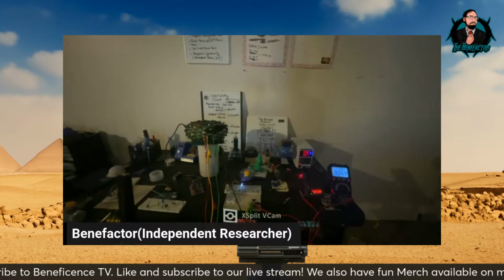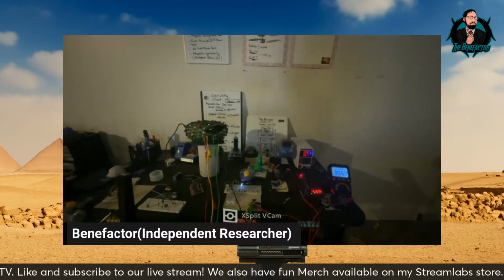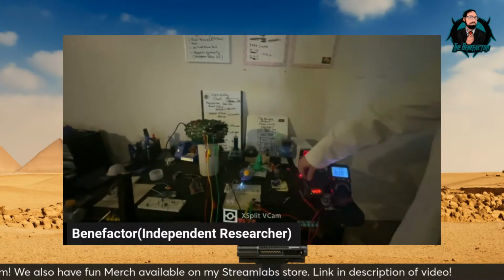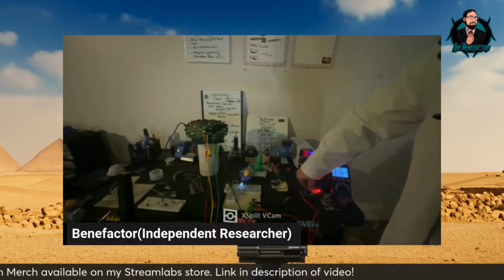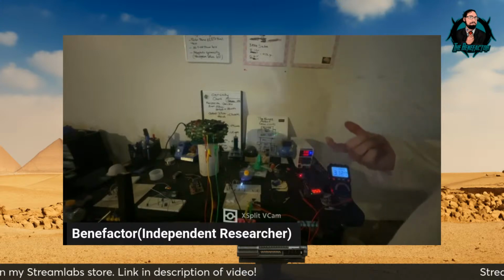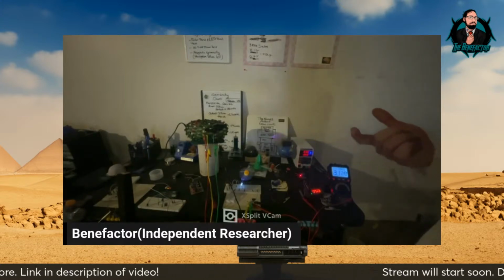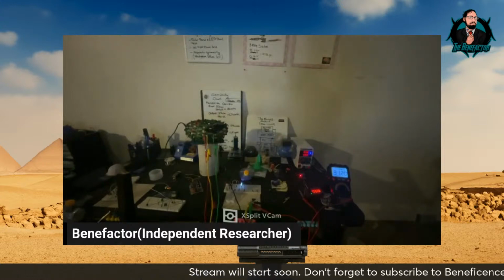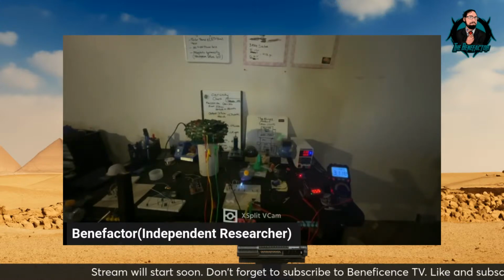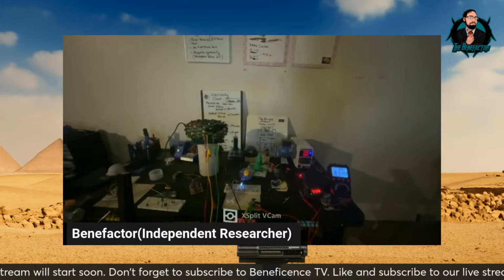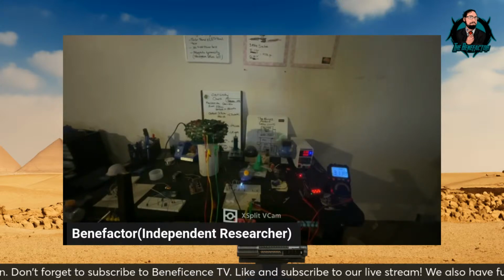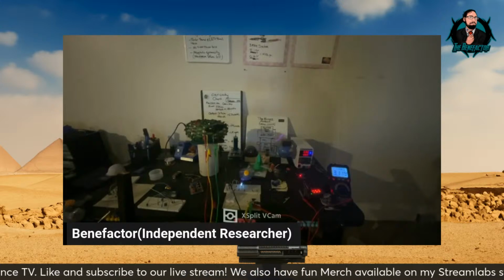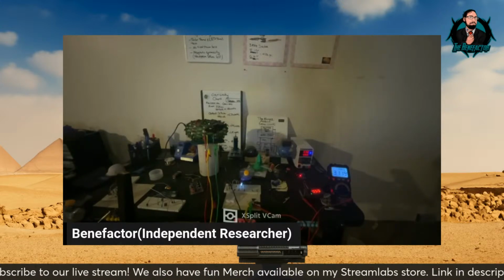Well, it should drop if you remember your wires are crossing in your coil, so you're going to have canceled signals if you go up too high on your frequency duration. So that's the explanation then. Yeah, that makes sense. I'm going up too high. You're changing the frequency and then you see the drop. Okay, so it can't go above 50% duty. Otherwise, the voltage on the output just takes a dump. Well, yeah, because at that point it just thinks you're putting a solid signal in. Right, it's not really pulse.